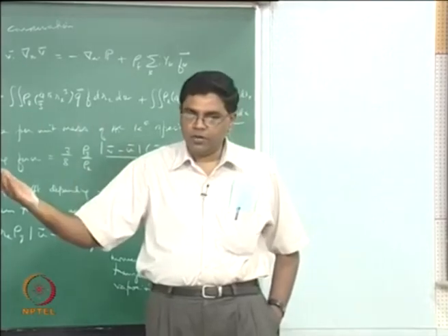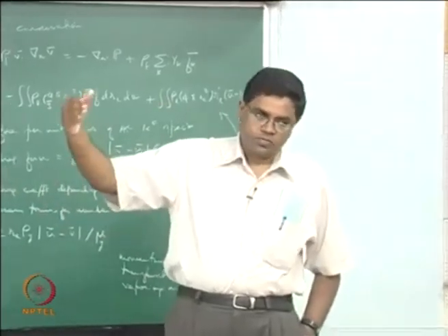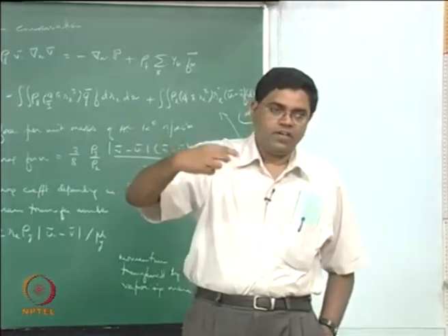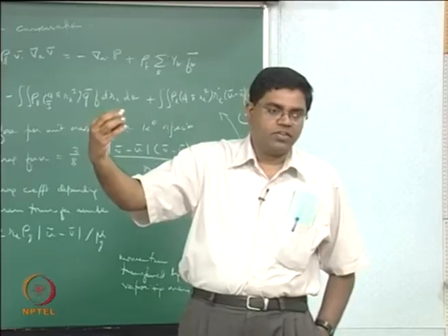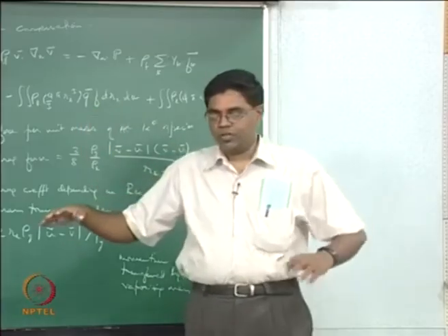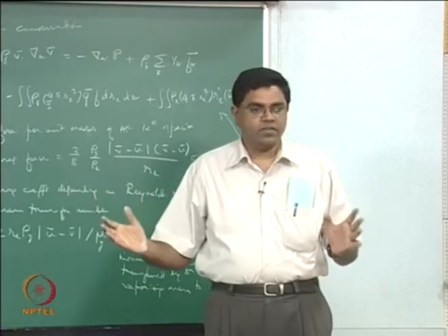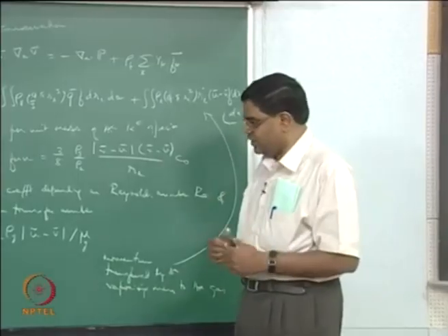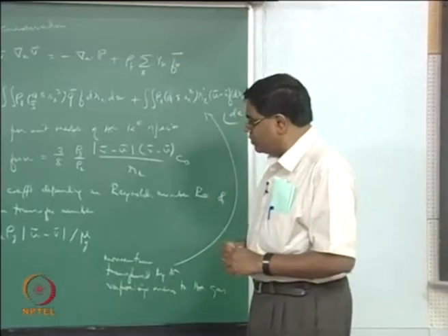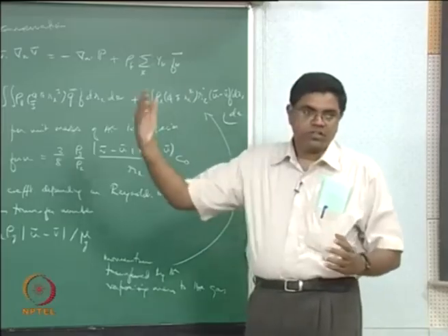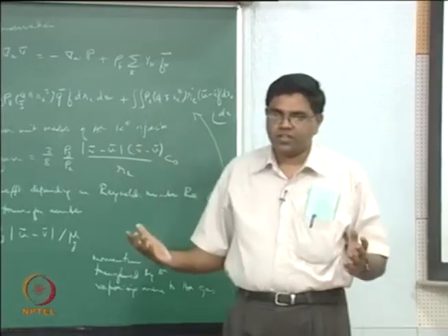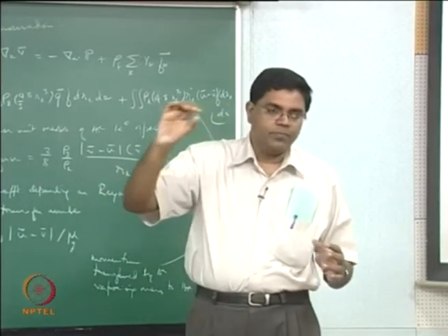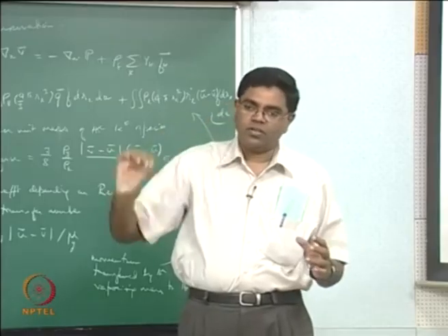following the turbulent flow around, but as it is moving it is also producing a wake behind it, and this wake is obviously of length scale of the order of the droplet size rather than that of the characteristic dimensions of your combustor or your burner, which the overall prevailing turbulence is of a length scale of. So what happens is, you now have these multiple length scales of turbulence, the larger length scale corresponding to the combustor geometry and the small length scales of the wake turbulence from these droplets.